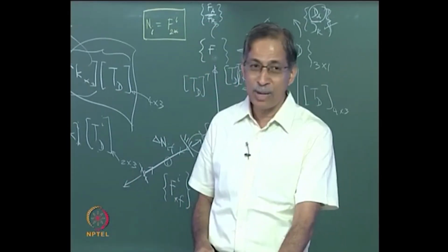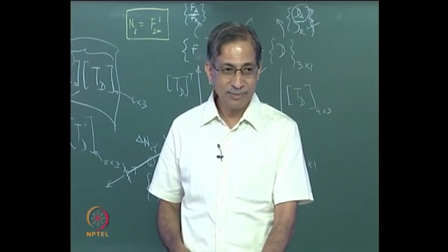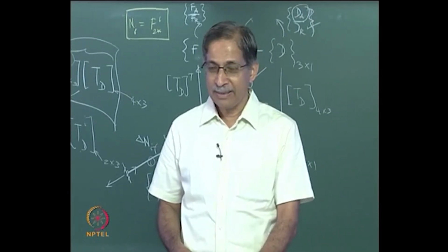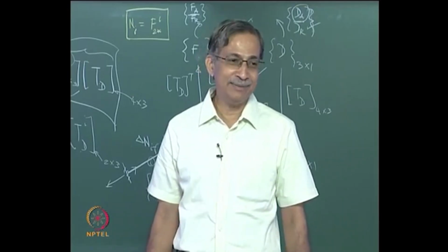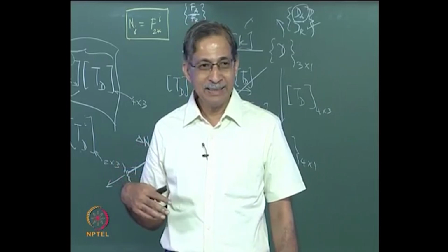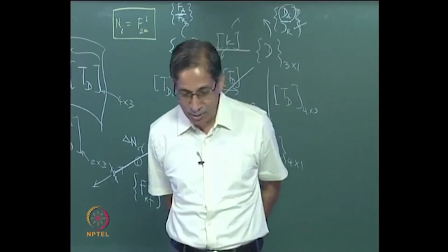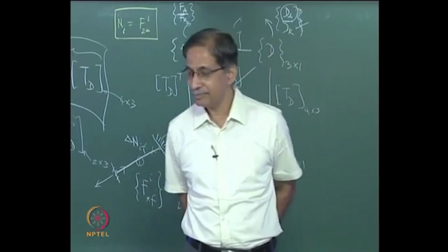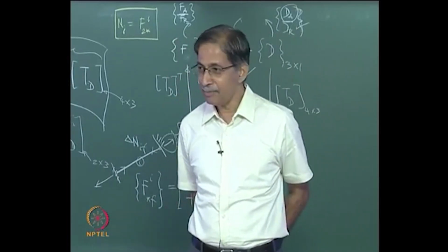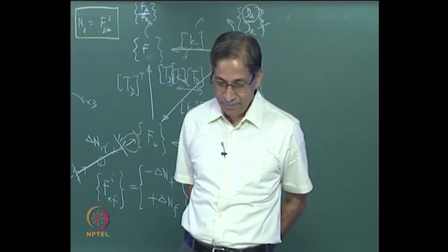For this loading, do you have an answer? Do you have axial forces? Can you find them out? Sure you can. But it is statically determinate, so I do not want you to forget your basics. Can you quickly draw the axial force diagram? What will be the total reaction at D? Tell me the number. 110. 110 kilonewton, right? Show me how the axial force varies from A to D.